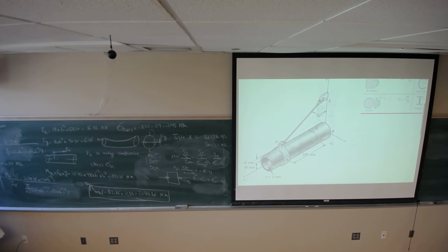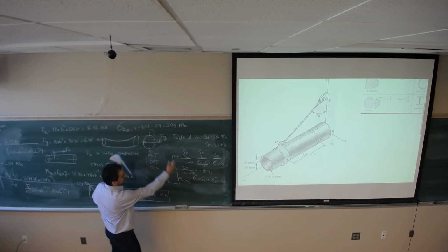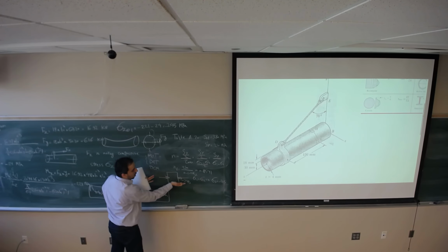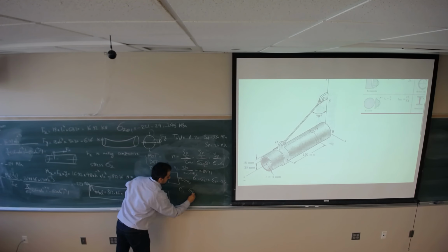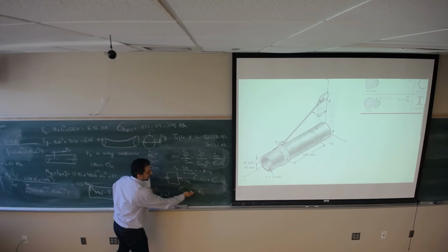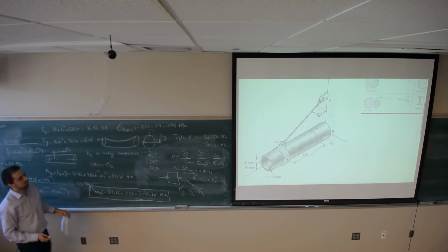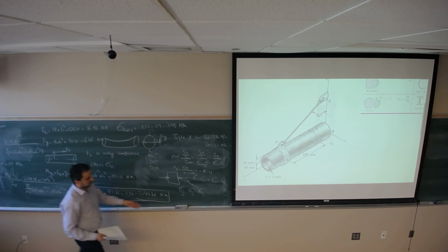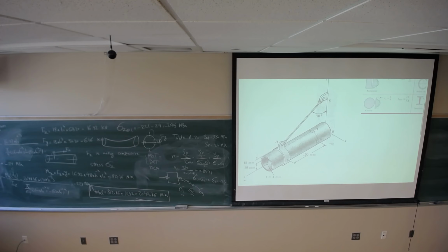Where did you get 245? Here, sigma 3. This is the stress element that we have. There is no shear stress, there are no other normal stresses. So it's telling me that I have these three principal normal stresses, the smallest one is going to be negative 245, and these two will be 0. So it's going to fail. The factor of safety is less than 1, it's going to fail based on this load.